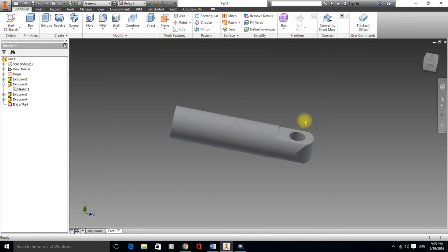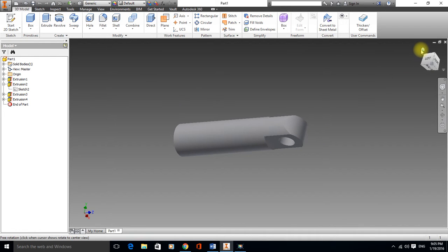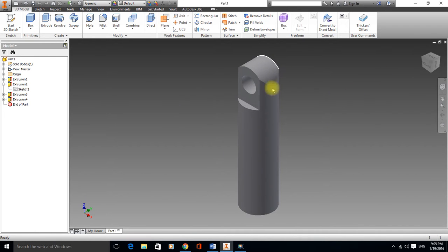Who knows? If there was a perpendicularity tolerance between one of these faces and that hole, this would be the better way, because we could do that face and that hole all in one operation. If there was no perpendicularity tolerance, there's no reason why we couldn't just hold it vertically in a vise, machine either side, and then hold it down flat and put the hole in after. Okay, so that's the two different ways we're going to be looking at this, and we're going to use both of those different ways to actually create the Inventor drawing.